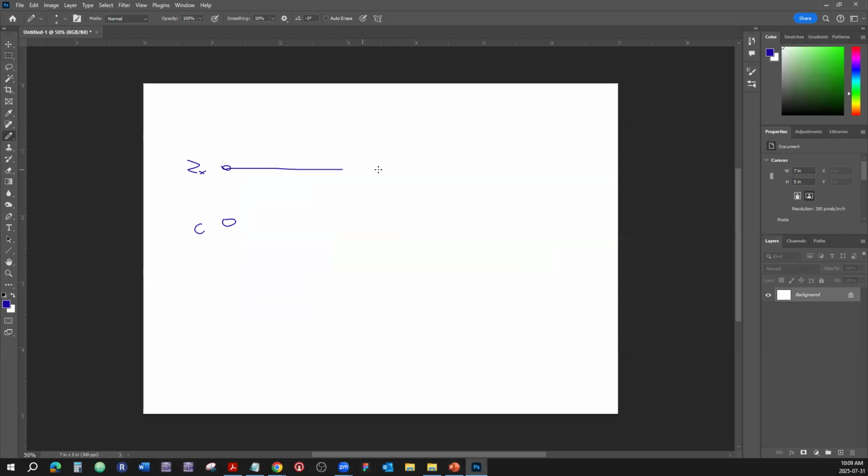So an end-of-line resistor is needed for that zone to see a certain type of resistance, whatever is spec'd by the manufacturer, 4.8 kilo or something like that. Sometimes it's a common thing.